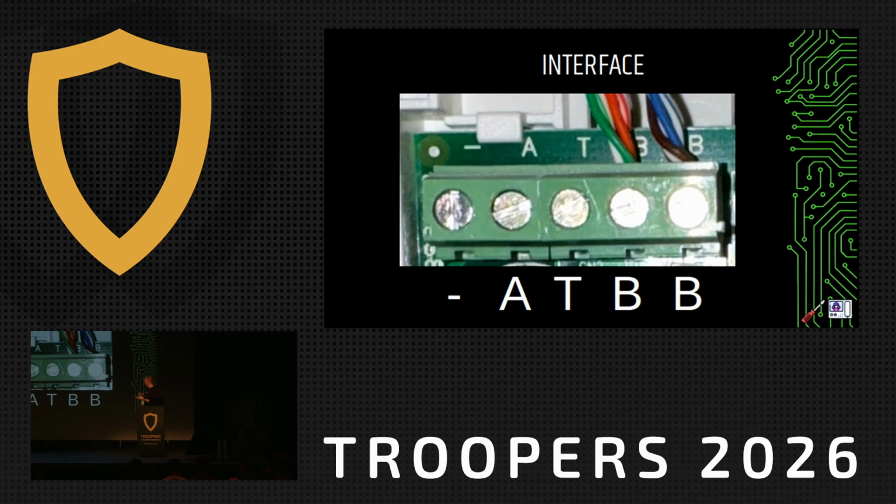Non-polarization is emphasized by both of them being marked the same. So B and B, right? And what we see here is basically the installer used the Cat5 cable to connect both wires of the bus, right? Just to limit the voltage drop. I think that's the reason why there are so many wires into each of them.